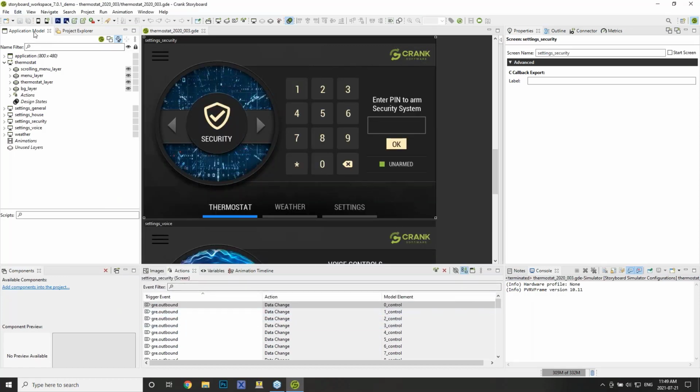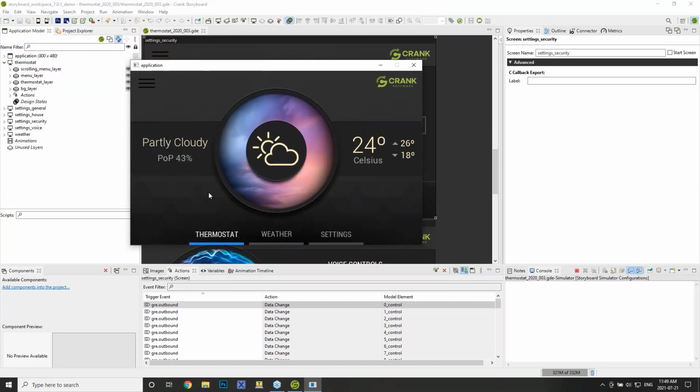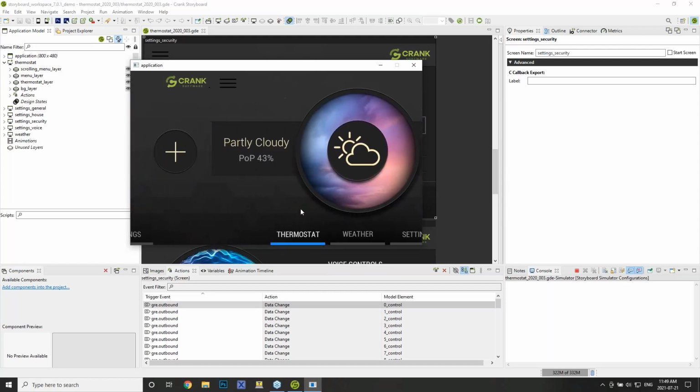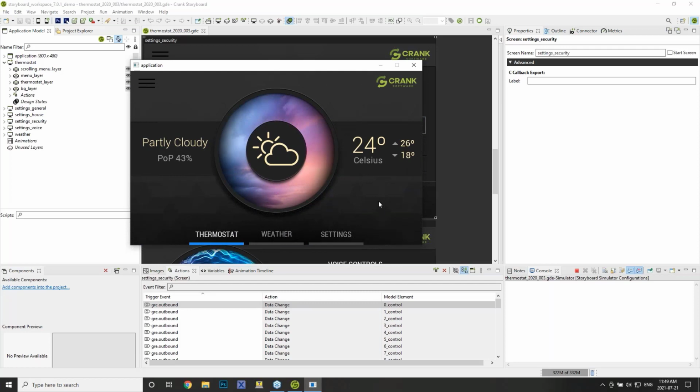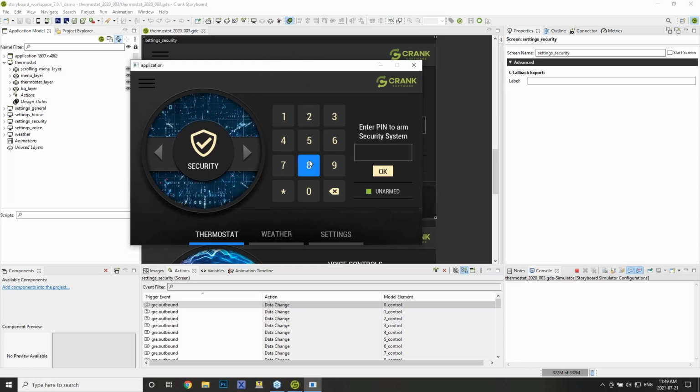And assuming I haven't done anything funky or misclicked when we run this, we have these nice draggable transitions. And the nice thing about this is because I've configured it and the engine is agnostic, it's going to behave the same way when you run it on a touch panel. The mouse pointer events are treated in a way that, whether it's a touch input or a pointer input, the engine handles that and translates that into the draggable events. So a couple clicks and you've got navigation set up. And you can see here, these buttons as well came in already pre-configured thanks to some just naming conventions in the design file.